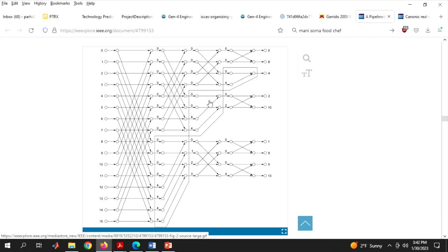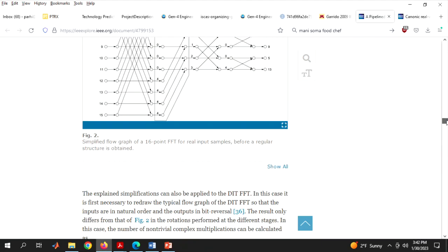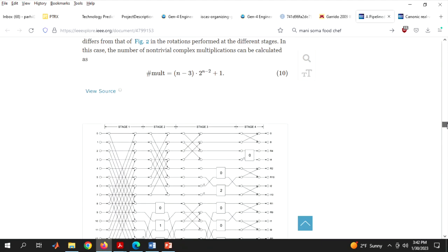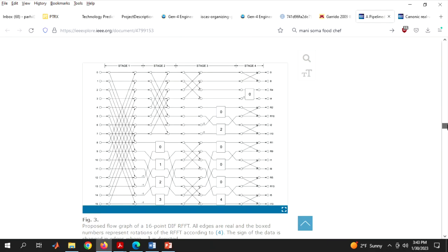These 2 halves, half complex becomes 2 real butterflies, and then 2 complex becomes 2 real, 4 half become 4 real, 2 complex become 4 real. So every stage we have exactly n by 2 real butterflies, and it really looks exactly like the complex structure.